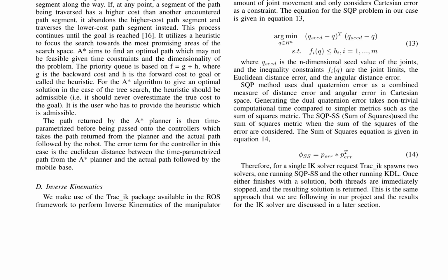The laser rangefinder has a range of 25 meters, 220 degrees field of view, 15 Hz update rate, and angular resolution of 1/3 of a degree. The IMU's gyroscope measures plus or minus 2000 degrees per second, while the accelerometers measure plus or minus 2 g. The gripper incorporates a 6-axis IMU and provides position and effort feedback. The entire task is performed in a ROS Gazebo simulation environment with the Fetch robot.